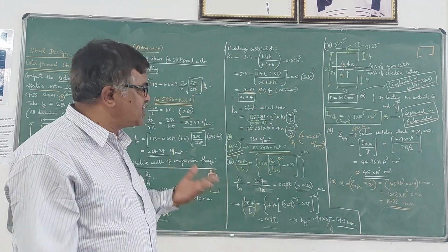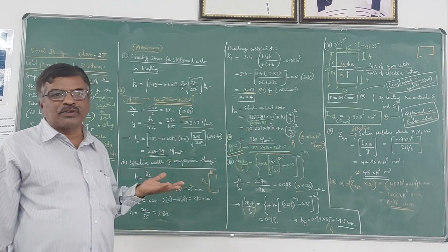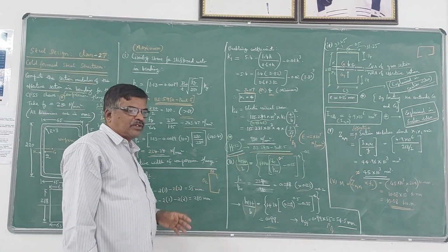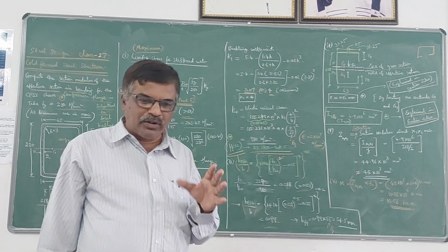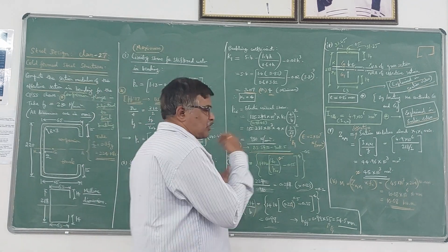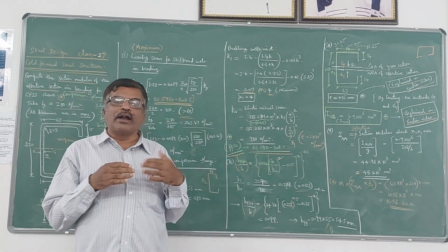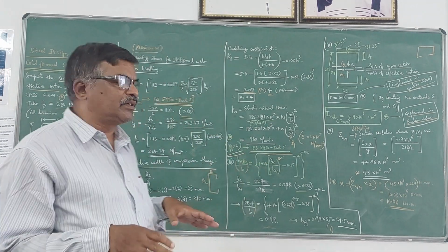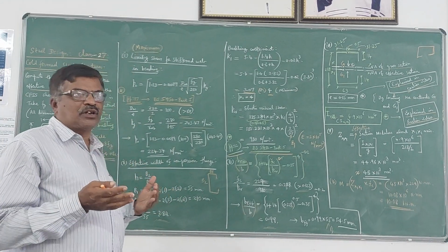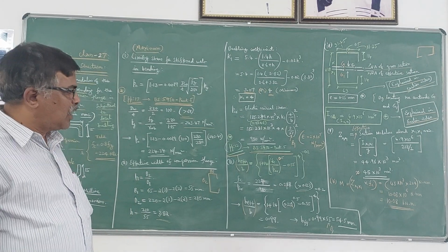So this is the basis for the design of beams using cold formed steel sections. Normally in the case of designs, we will be knowing the moment and shear values. For that we have to assume a suitable section, and cross check whether the section is safe against both bending and shear failures.